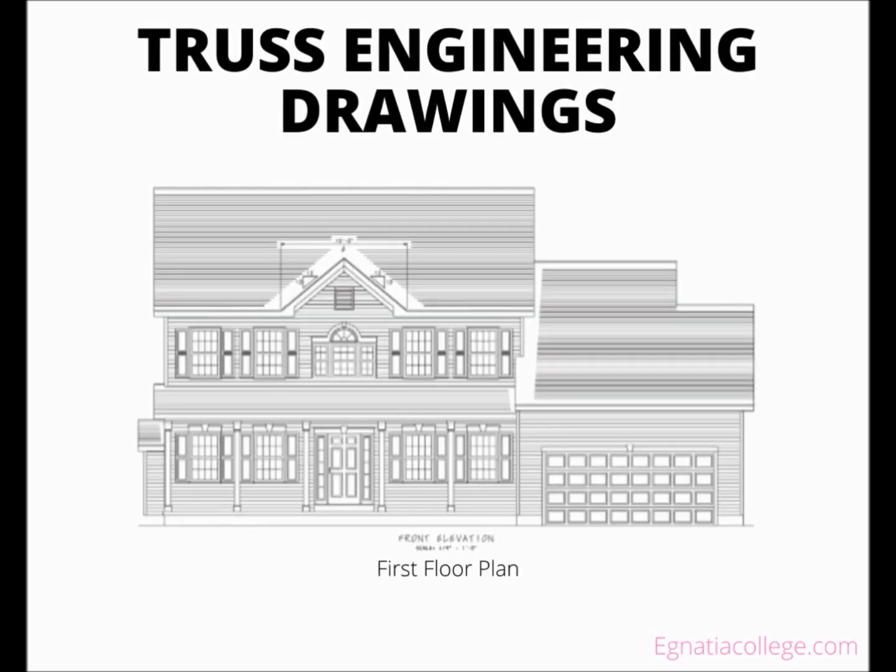Looking at the front building elevations in the figure, you can see that this has a small gable on the roof above the main entrance. Refer to the truss layout in the previous figure to see how this gable is to be framed. There is a triangle with 3 trusses, V2, V1, and T2GE. The main roof trusses T1A run beneath the trusses for the small gable, so the small trusses are applied on the main trusses after the main trusses are secured in place.